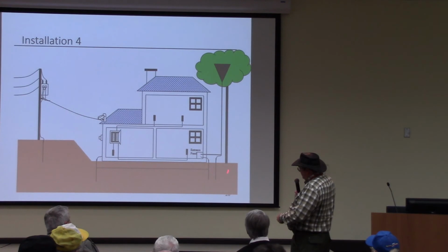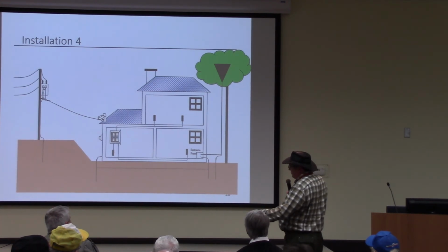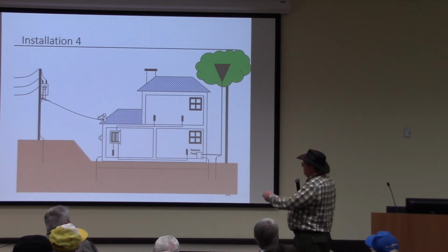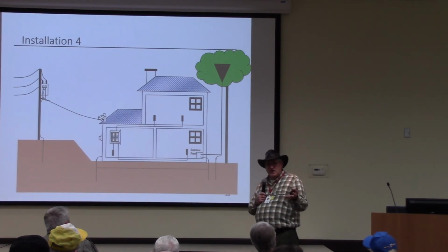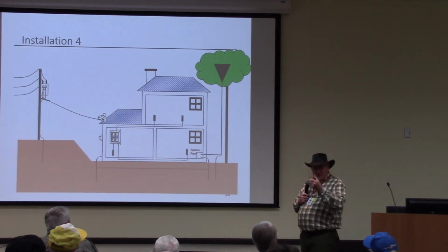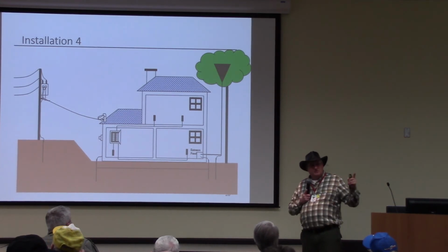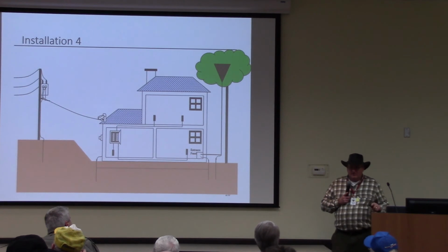We're trying to make this point look at the same potential as this point. If all of this came in right here, you could get away with not having this rod, but just have your multiple rods put in and have that as your one reference point. And then the potentials inside the house would not be that great.